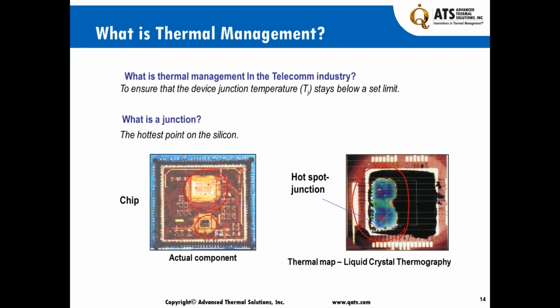Electronics cooling pivots around junction temperature, not the approach air temperature to the device, not the air temperature of the system or the temperature on the board, etc. It's the junction temperature of the device that we have to manage.